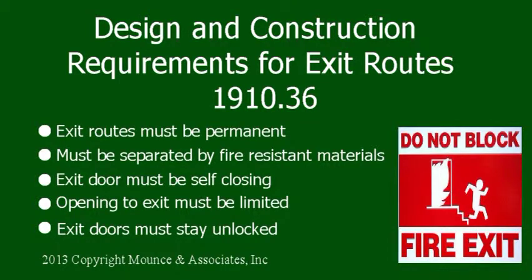The exit must also be limited and only those necessary to reach the exit discharge. Exit routes also need to be 28 inches wide and 7 feet 6 inches tall. It is important that exit doors remain unlocked at all times.